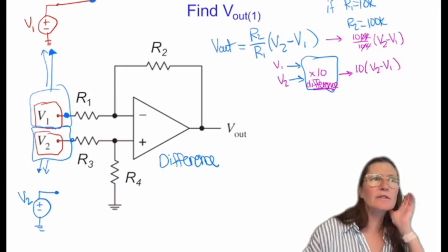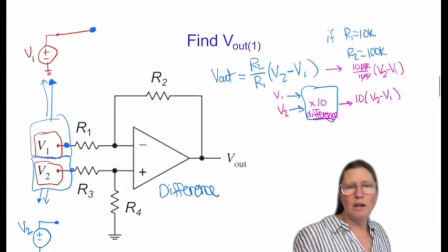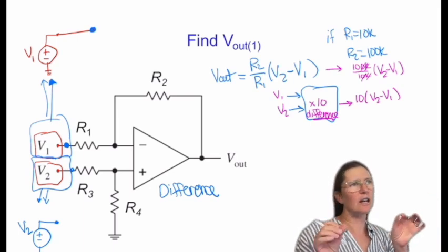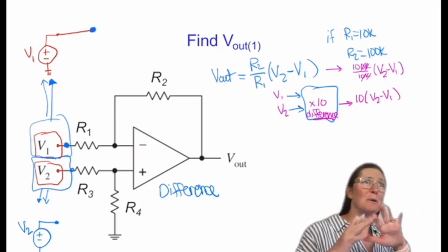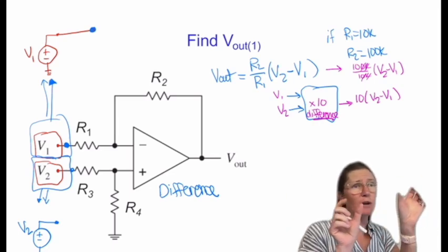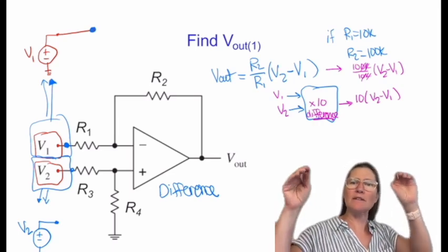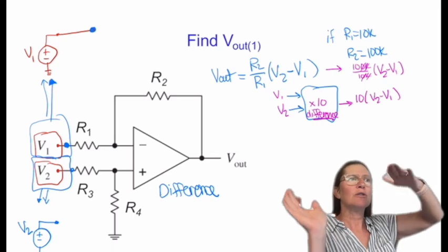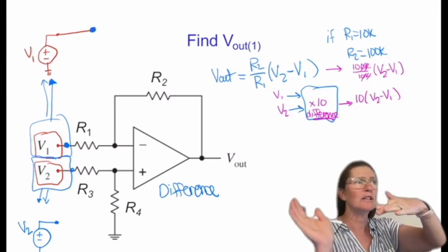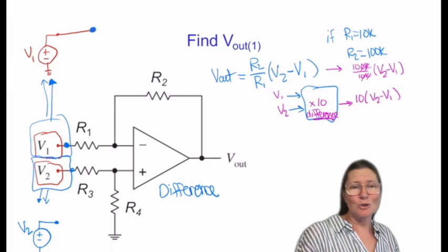And that's because of this configuration, the way it's connected up. So this sounds like a great way to, say I have two strain gauges on the RoboBee, and I want to compare the two to see what my difference is going to be, and then interpret that to mean something like this wing went down and this wing went up. So a small difference turns into an actual physical difference of something happening. So this sounds like a great thing to do and use.